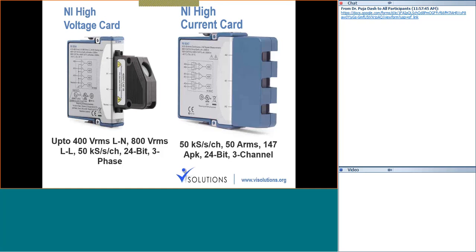So we have NI cards up to 400 volts RMS line to neutral, so 800 volts RMS line to line, and up to this you can do. Since I'm making waveform measurements, this can measure up to 50 kilosamples per second per channel. So you can get three-phase, oscilloscope type of measurements. If you don't want that type of measurements, let's say you want instantaneous measurements, of course NI also has DMM cards available, where you can make instantaneous measurements up to 1500 volts RMS.